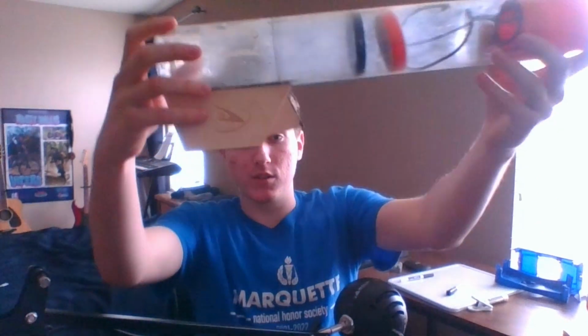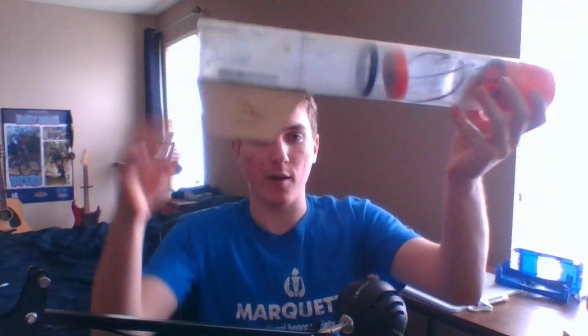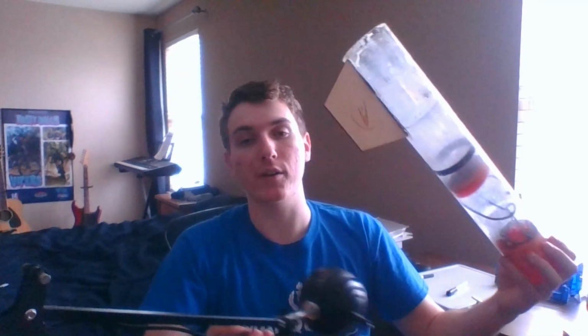So now I'm going to explain how drag works. First I'm going to explain the equation for drag. You've got a coefficient in front of it, which is just a number based off of the shape of the object. You've got projected surface area. You've got velocity. Those are the things that affect drag generally. I might have missed something, but for this conversation, that's what matters.